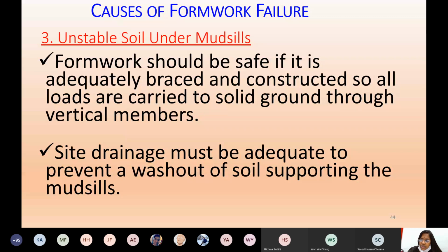If there is a chance of raining, all the rainwater should be collected out so there is no waterlogging, and no problem for the scaffolding. You have to check all these points before you go for concreting. On the day of concreting, that morning you have to go to the site early and check whether there is rain, and check each support one by one. If it is 100 supports, you have to check one by one whether each support is properly holding. Is there any problem, swampy or marshy land, some kind of loose soil due to raining? You have to remove it properly, harden it, and then go for construction.